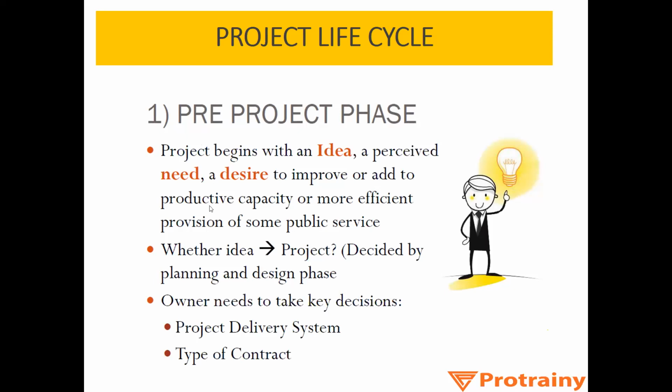When you want your idea to become an actual project, the owner needs to take key decisions. What are the key decisions that will be taken by the owner? The project delivery system, what he wants to build, and the type of contract that he wants to work in, whether it will be an item rate project or a lump sum project, how he is going to give the contract. So this is the pre-project phase.